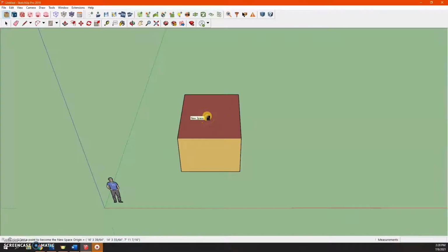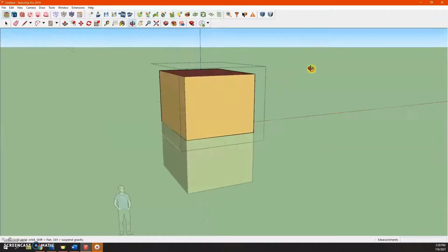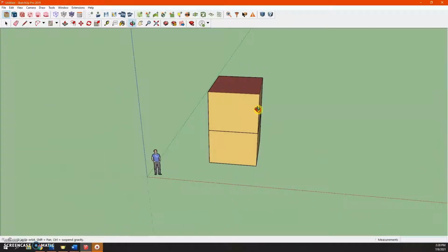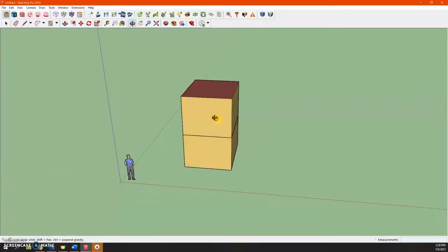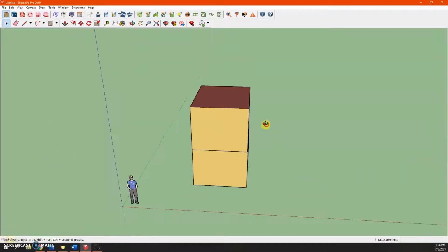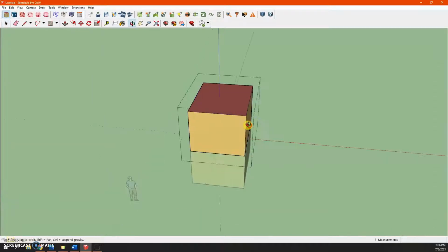Let's add a second one since we do have 2 spaces. And keep in mind for our spaces, it's floor 1 and floor 2. And our thermal zones is floor 1, floor 2A, and then floor 2B. So the spaces and thermal zones are not one-to-one. So right now we have 2 rooms, and we have to create a third one in order to fit our third thermal zone. So also to mention, the rendering conditions are all white just because we have yet to define them. So now we're going to make that third room for the third thermal zone.